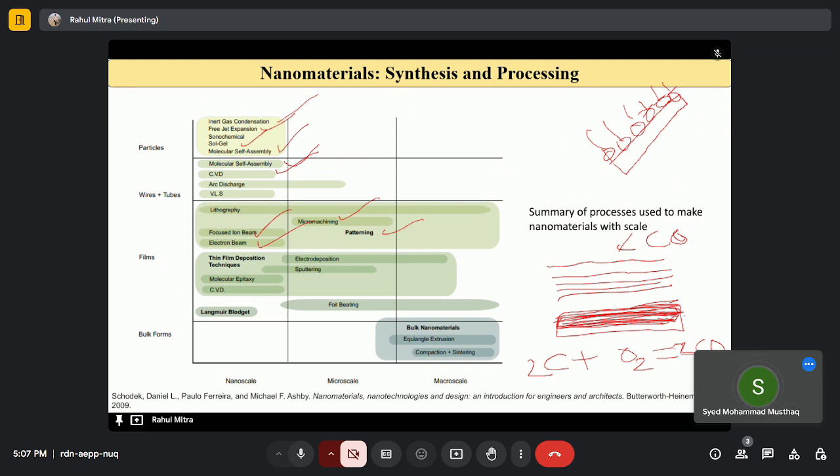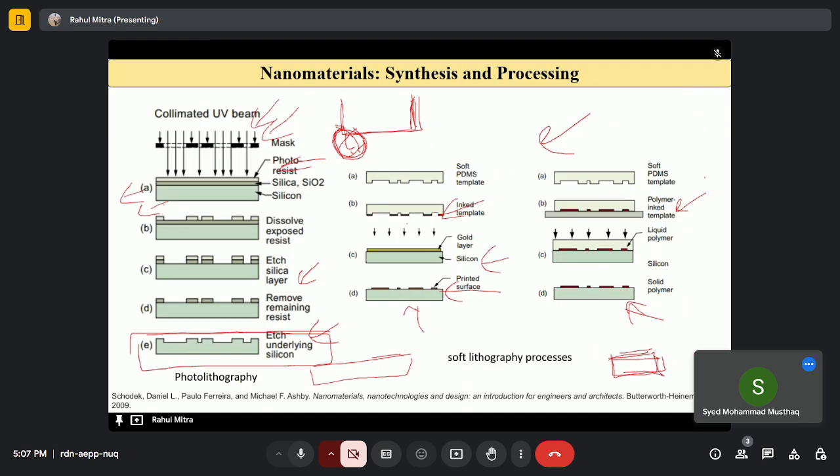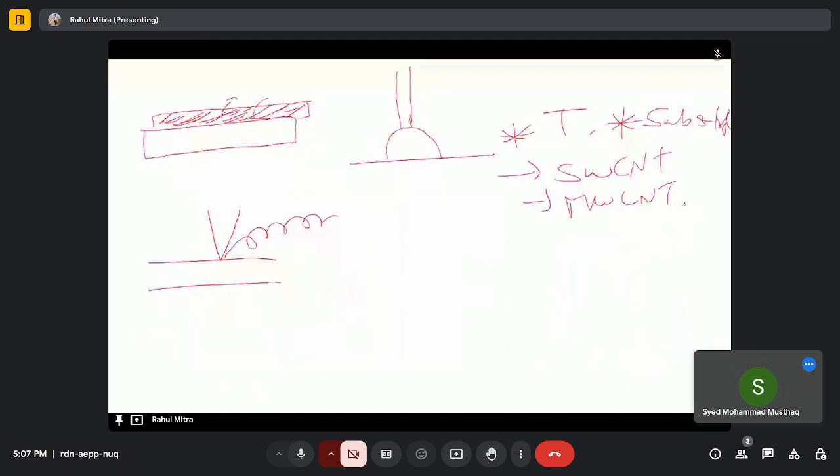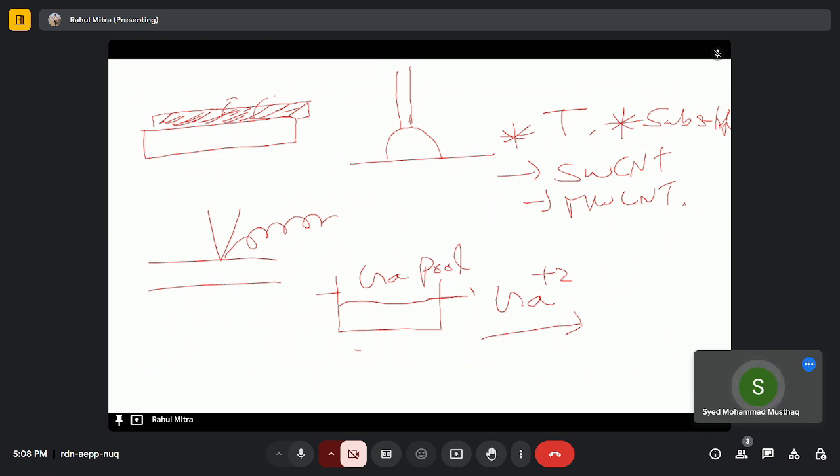For example, if I have a gallium pool, and on the gallium melt, if I apply enough temperature or an arc discharge at the surface, we have gallium ions, and these gallium ions are accelerated and impinged, bombarded onto a surface. Then we have a sputtering of atoms, where the atoms are removed from the surface.